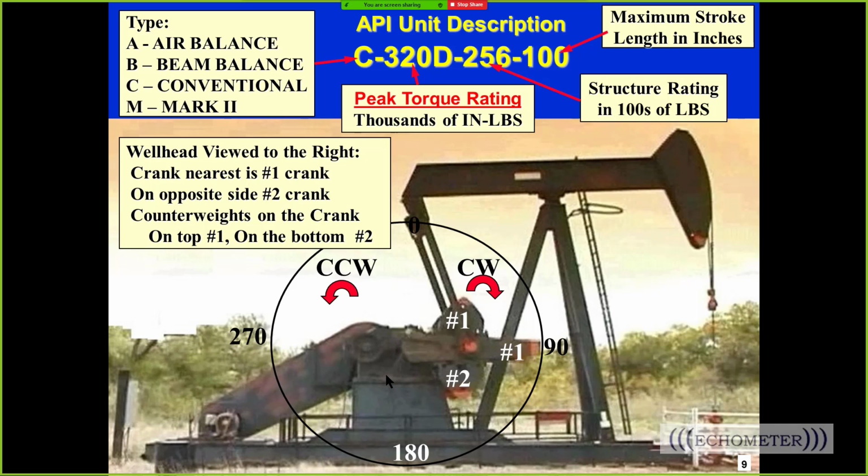When you look at the pumping unit from the side, the polish rod would be in your right hand as you were facing the pumping unit from the side. This rotation is clockwise, and this rotation is counterclockwise, and that's one of the things that you should record if you're trying to do mechanical torque. The power probe, though, typically is just used along with the dynamometer data.